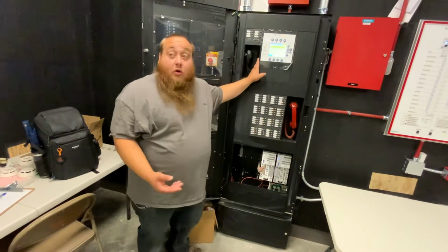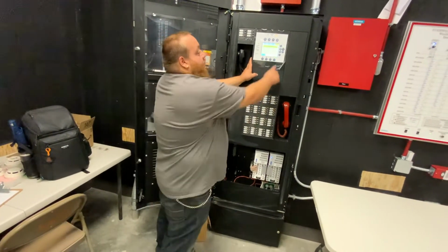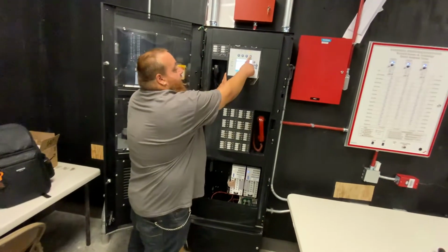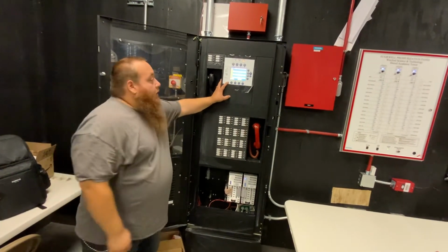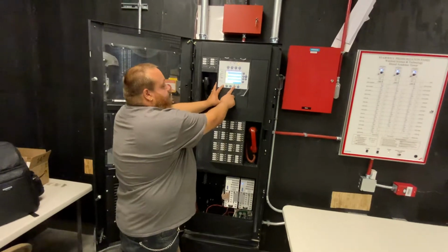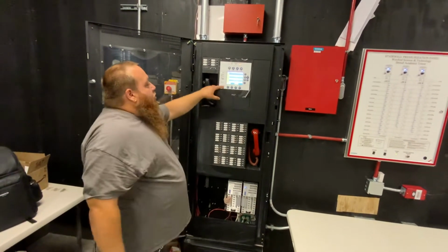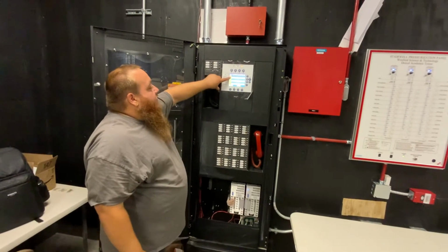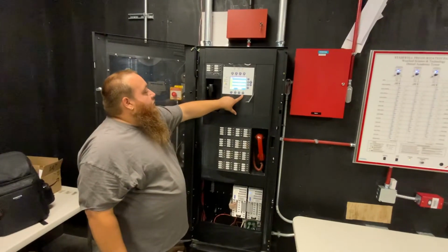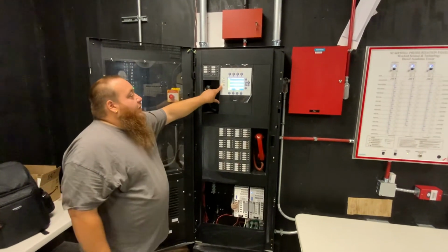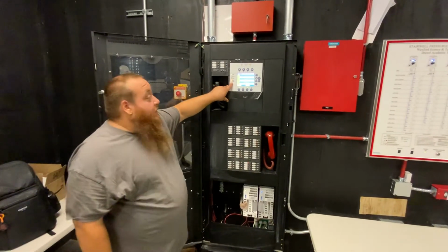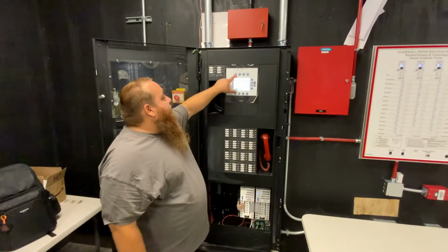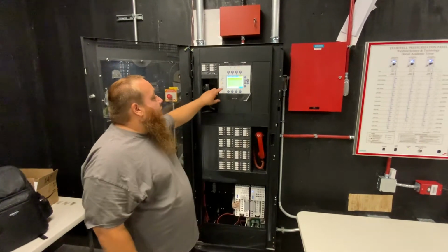When you want to disarm something in the building, you have the enter menu and your function keys, and all your disarms will be here. You have a few of them, but when you disarm something, you would hit your X button, you would execute it, and now that you have something disabled on your system, it's going to say, hey, you took something out on purpose. At any time there's a change of state on this system, it'll tell you.